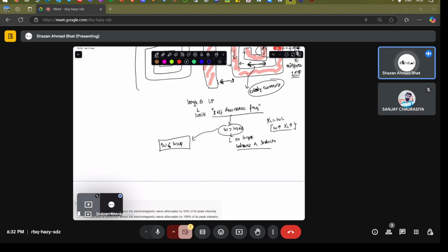We will see there's a plot of inductance, which goes to a maximum. If this is inductance in Henries, and this is frequency in gigahertz, then the inductance reaches a maximum, changes sign, and looks something like this. So this is positive inductance, this is negative inductance, and there is a sign change around this particular frequency, which is the self-resonance frequency of an inductor.